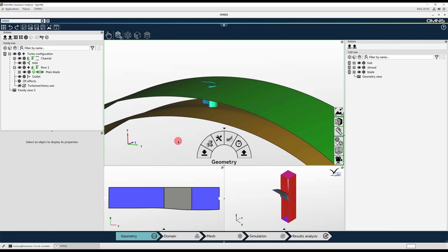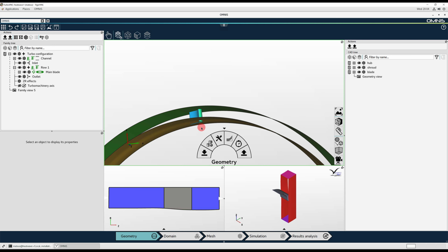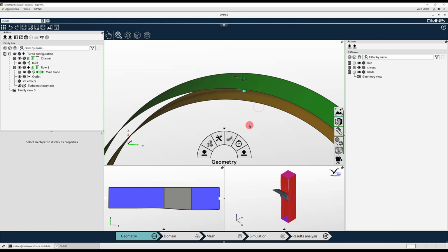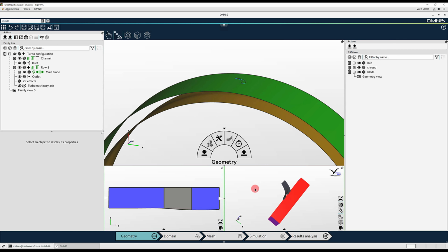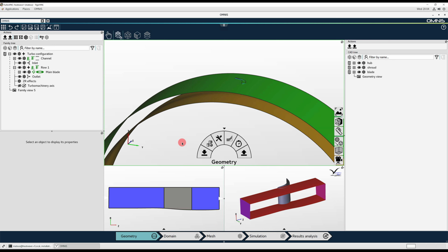We can consider the example of an axial turbine stator row with axisymmetric hub and shroud curves, which has already been linked and set up in the geometry context. The procedure up to here is simple and is covered in a dedicated video for automatic turbomachinery structured meshing. Let's take the example of defining a non-axisymmetric hub for the current configuration.